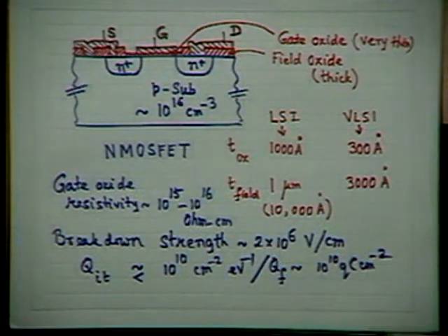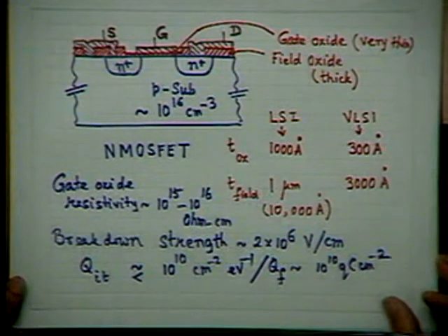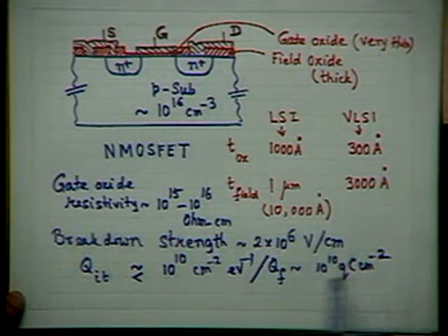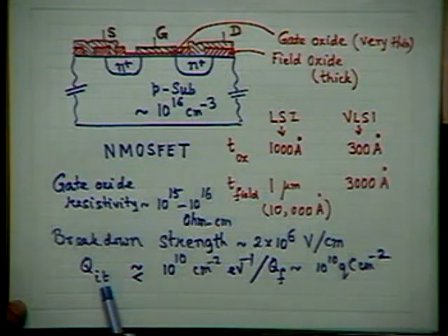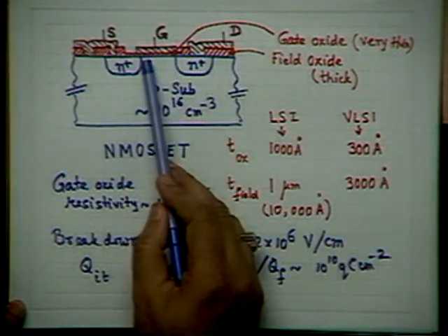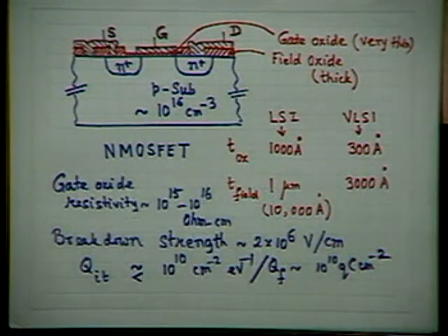Q means electronic charge. You remember that some device physics was discussed quite a long time ago. And remember, these are some of the very important features which must be maintained. One is the interface state trap density. The other is fixed oxide charge density in the gate oxide interface. This quantity should be controlled precisely. Otherwise, you are not going to have a very satisfactory MOSFET.